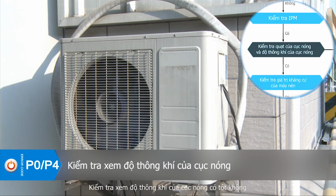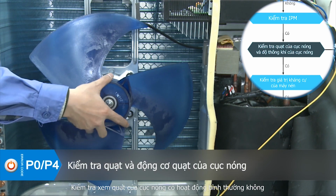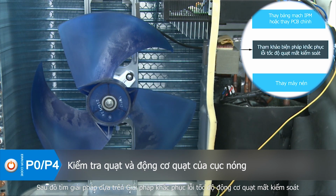Check if the ventilation of the outdoor unit goes well. Check if the outdoor fan operates well, then find solutions according to the solution for the malfunction of fan motors being out of control.